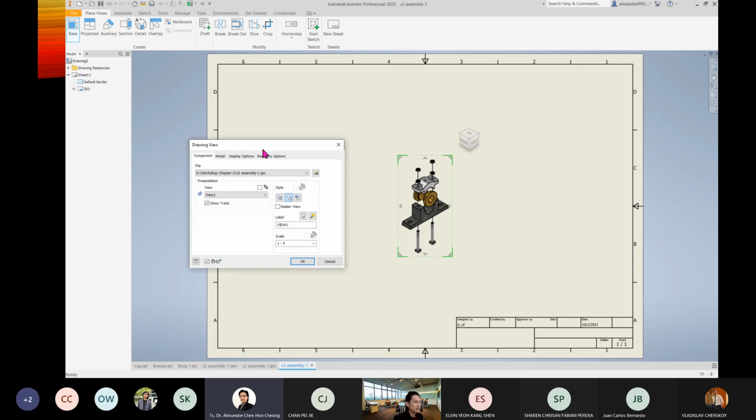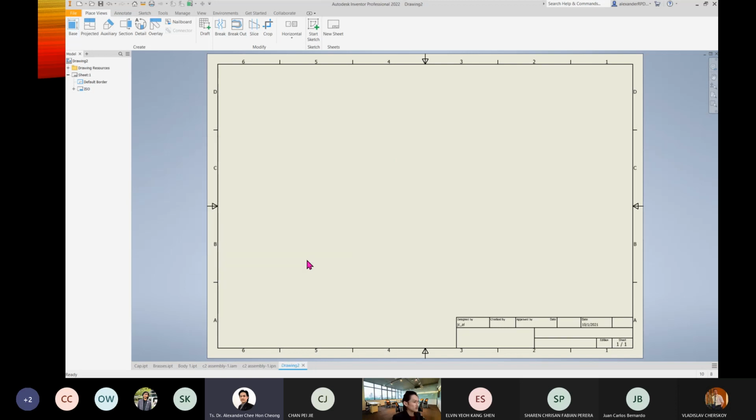When you do a base view, by default, if your Inventor presentation is open, then it will detect the presentation, or else you can still select the file from the ones open over there. Sometimes it will list the files from the project, but it gives priority to the file that is open. That's why in the beginning, you don't close it first. Open it next to it. Which drawing? ISO, IDW. Okay, so do it one more time.